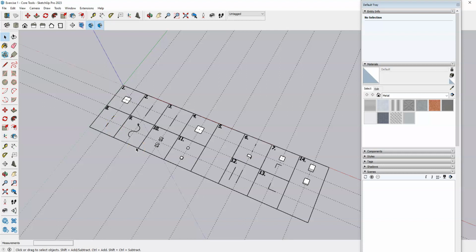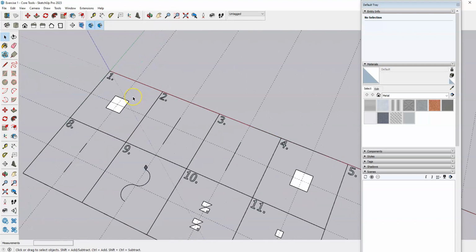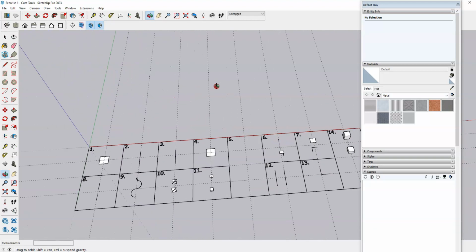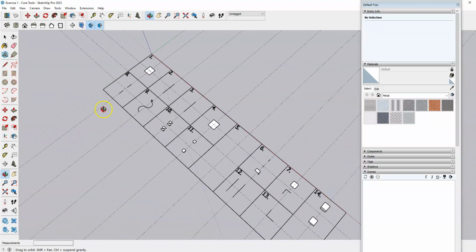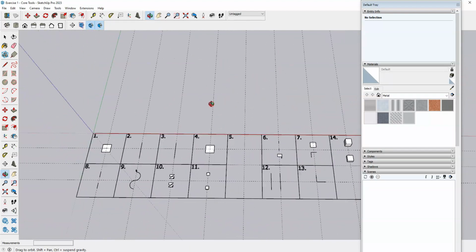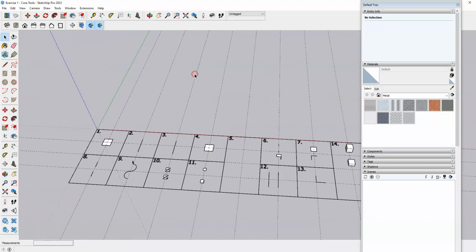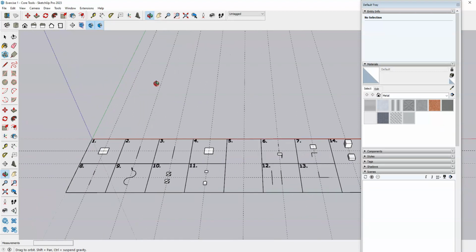do. So your scroll wheel is actually kind of a tool itself. So you can scroll in or scroll out with the scroll wheel. You can also press and hold that scroll wheel, and it turns you into more of this orbit feature where you can swing yourself around the model. So I'm just pressing and holding on that scroll wheel to be able to do that. And then if I do that same thing, press and hold, you'll see that red and green, my mouse turned into that orbit tool.